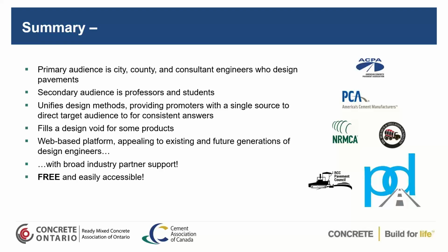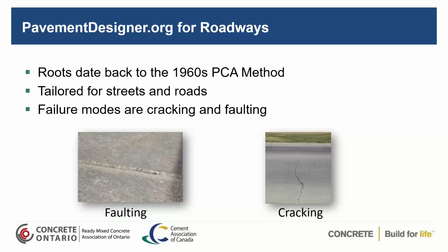So basically what we're doing here is we're providing one software to allow you to do a whole suite of different types of designs, which is free online, and has broad industry support on the results that it provides. Myself, when I'm doing a design, I actually like to use the StreetPave software and this to check them one against the other to ensure that I haven't made any assumptions that I shouldn't be making. But it's always good to try to check at least 2 different design methods when doing a pavement design.